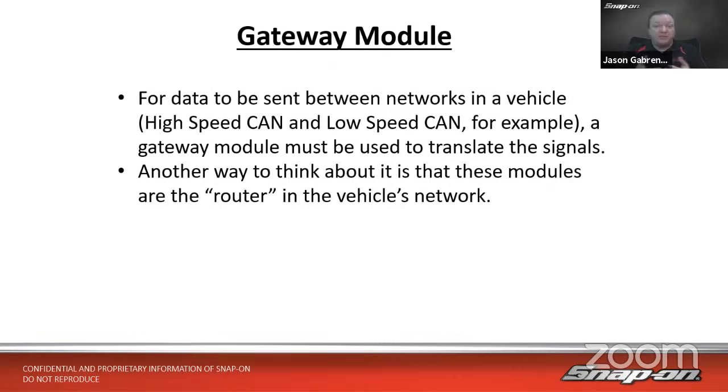Oftentimes on a car, it could be called a gateway module. Oftentimes on a car, it might not be called a gateway module. It could be in some other sort of module on the vehicle. I think of the signal acquisition module on a Mercedes. That works often in that type of way. Body control module oftentimes can be your gateway module as well to translate those signals between all of them. Let's use just a sample scenario, for example.